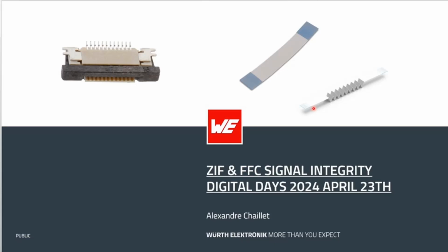So ZIF and FFC is a very common connector that everyone has used a lot for many years now. And you use it not for power, of course, but for signal. And in most of the datasheets, you will not really find the information of what kind of protocols you are able to use with it, what is the bandwidth, what is the impedance, all that information that should be necessary to properly use a signal connector.